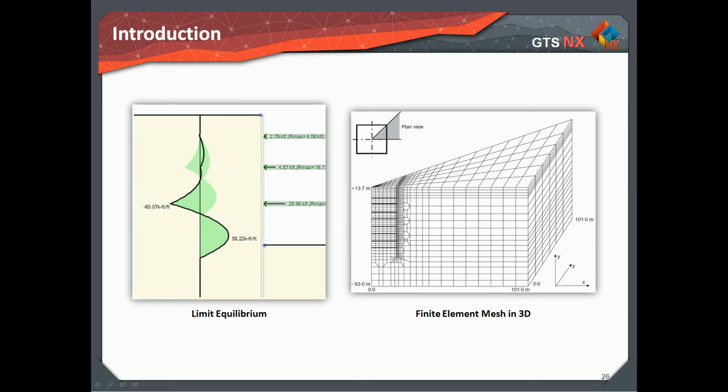Most of these methods simplify the 3D problem to a 2D problem. Fundamentally, limit equilibrium design method for the analysis of embedded retaining structures assumes the wall to be rigid and the soil to have a rigid, perfectly plastic behavior. The earth pressure deriving from the interaction depends on the expected movements of the wall and the mobilization of active and passive lateral earth pressure triggered by such movement.